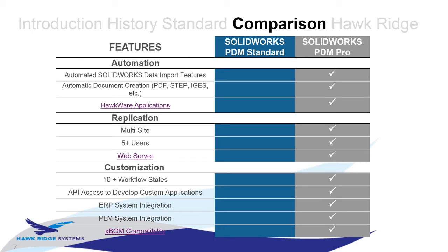So before 2017, we had access to archive server replication. What that means is you'll have the file server be local to both teams. That way, when they download files, they don't have to download over the network. They just download locally. With the introduction of 2017, SOLIDWORKS has made some changes where they start allowing database replication. So that's something to look forward to in 2017 as further development on it improves. But there's database replication available.